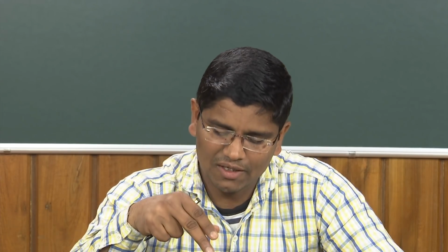In this way, what one can study with the pin on disc experimentally is the 2-body abrasion and 3-body abrasion. If I want to study the delamination of coatings, you can do scratch testing. Scratch testing is also one of the ways of doing the tribological test.